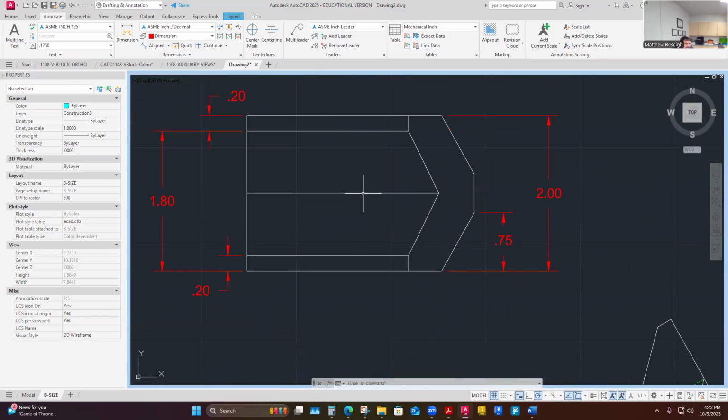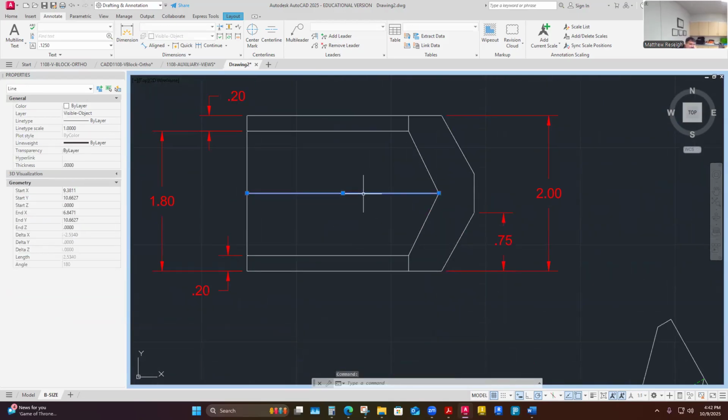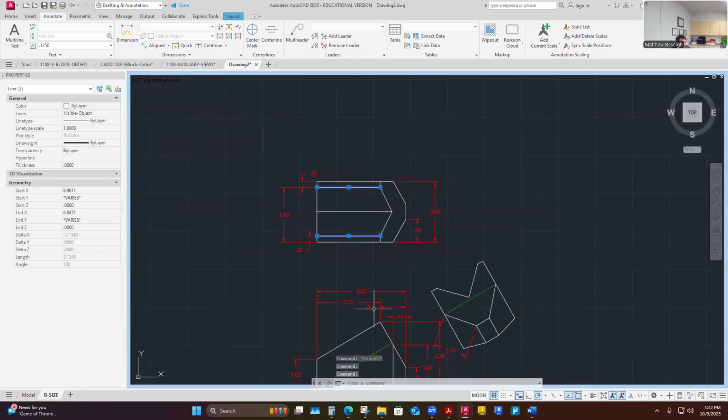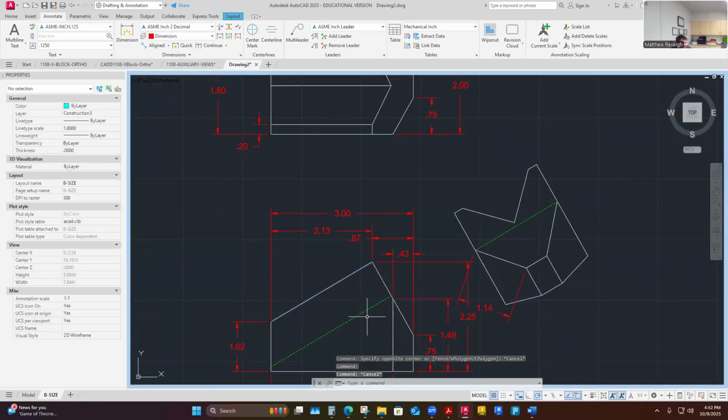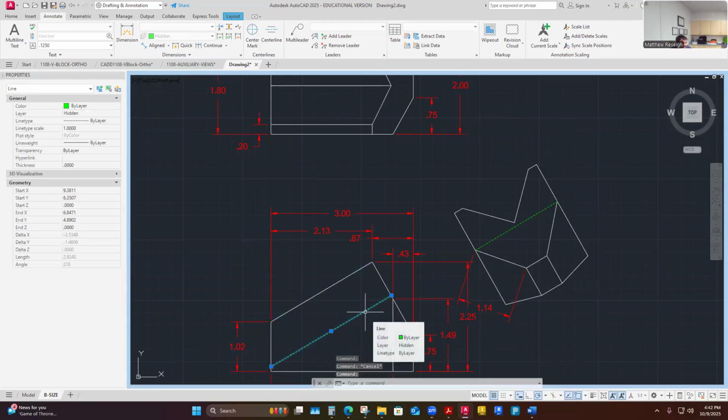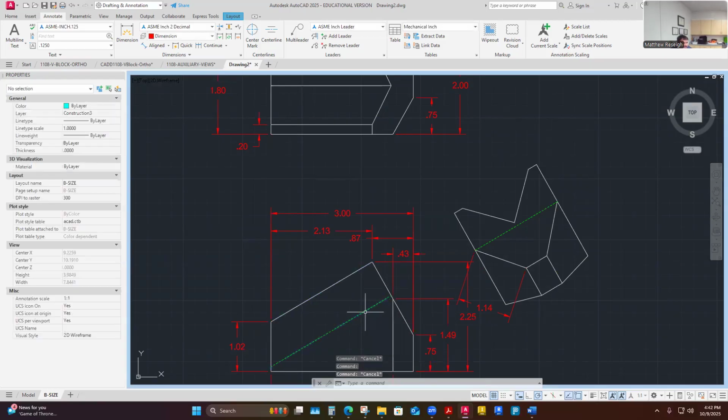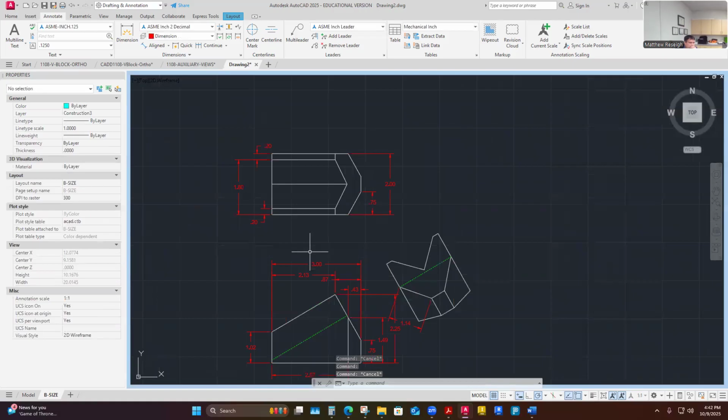What they have is this is a foreshortened line. It's going down and away from me here. So is each edge. All these edges are foreshortened. I pick up the true length of those here, and I pick up the true length of the V right there. But it's a hidden line. I don't want to dimension to that. So what can I do with those V's?